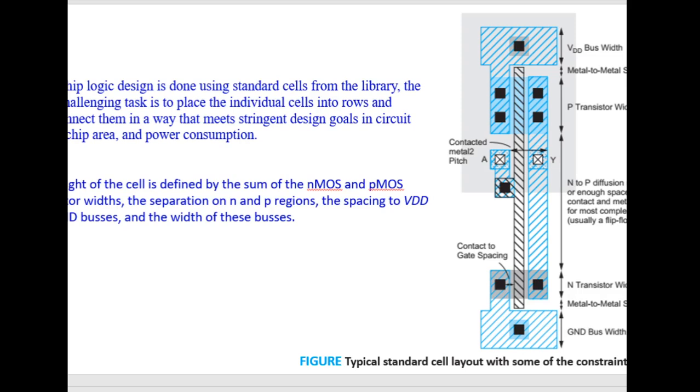This black colored rectangle is actually the polysilicon that connects the PMOS with NMOS again. Not a channel exactly, it is acting as a connection, a connecting wire between the P transistors and the N transistors.